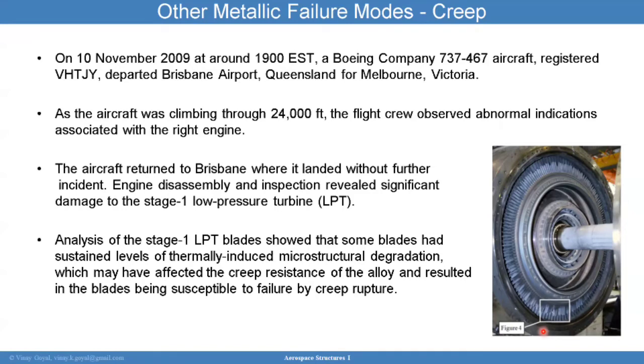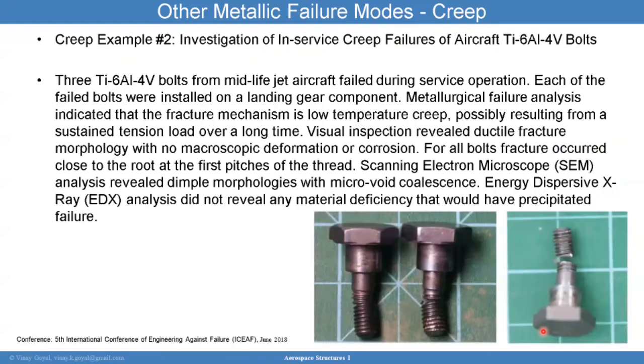So that's one example where we've seen that. Now, we've seen this also in the rocket engine industry, and also in spacecraft applications where you're trying to deploy a slat or a deployable mechanism that's stowed for a long time. Creep can then cause it to not return to the deployed configuration, causing the spacecraft to not be able to perform properly because the deployed mechanism was hindered by the creep mechanism, due to the sustained loading condition.